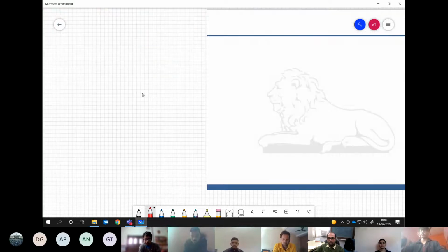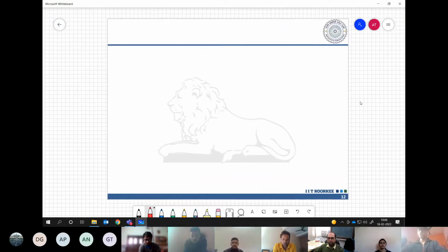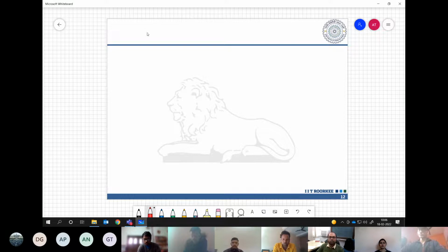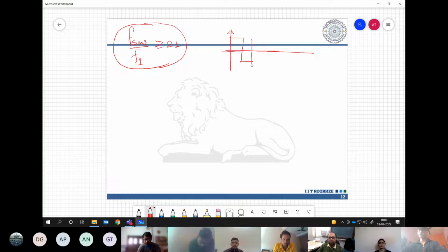So whatever we have discussed so far, based on that, we have understood that if we have the freedom to make the ratio of switching frequency and fundamental frequency high, let us say more than this number, then it is not advisable to go by the methods where we compute the switching angles within the quarter cycle and then we realize the waveform. This may not be a feasible way because there may be so many angles over here and it may become difficult eventually to solve all the angles and then you store it somewhere and then take it out for realizing the waveform.